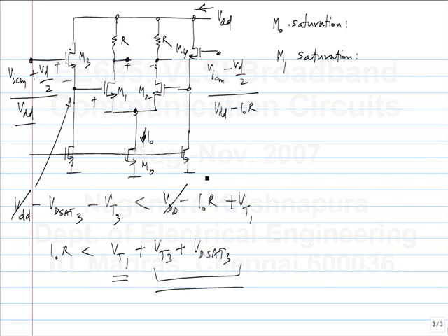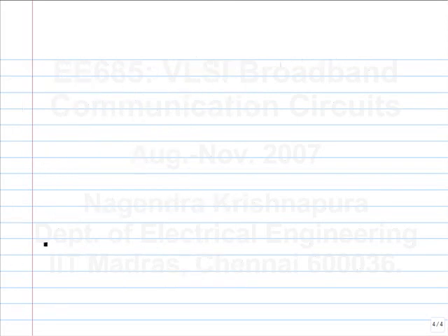But so far we have only a buffer and an inverter. Inversion is free because you can swap the wires. How do I make more complicated logic with this? I want to make an AND gate. What do I do? Let's forget these source followers and consider just this version. That is just an extra detail. We can always add it to every input if we want to. So let's look at this.